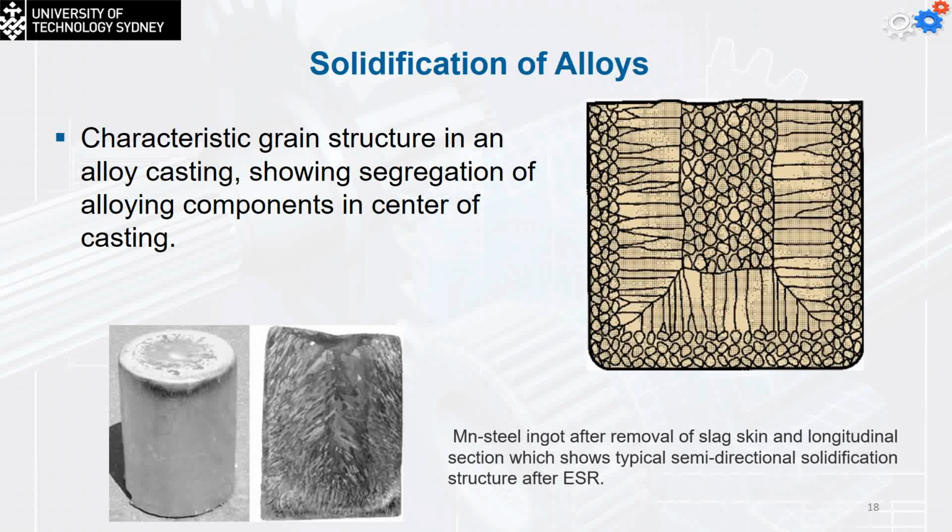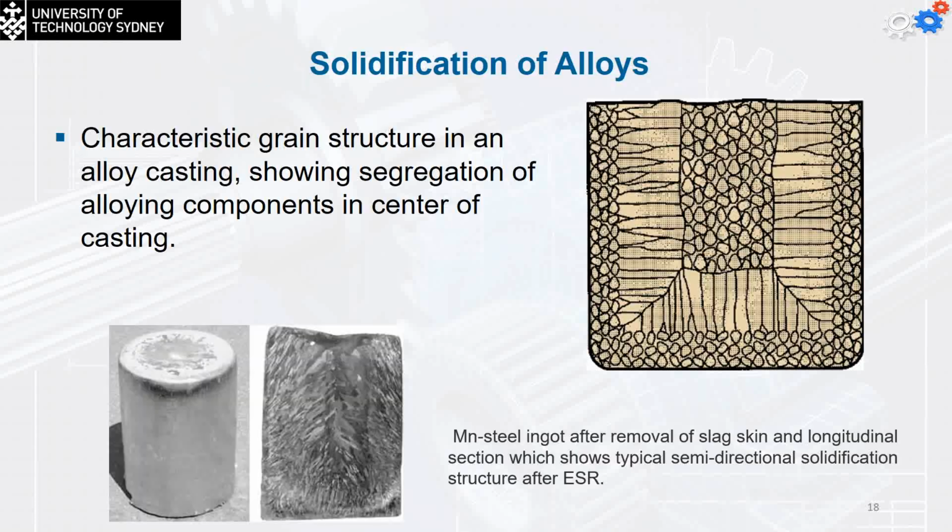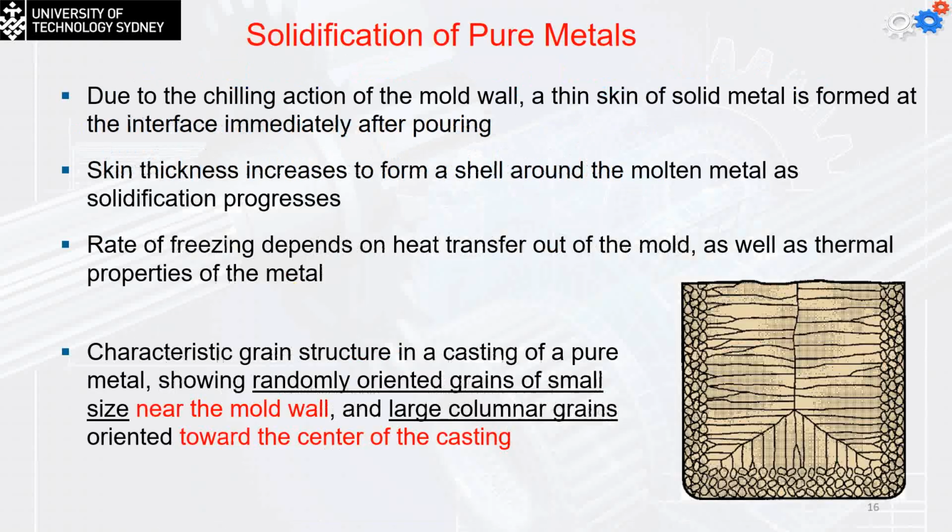Solidification time can simply be calculated. Basically, what is the factor that will decide the solidification time? If you take a look at this part and the previous one, the solidification will start at the wall, then go onward. That means a bigger part is going to take a longer time to solidify. So the volume is the main factor.